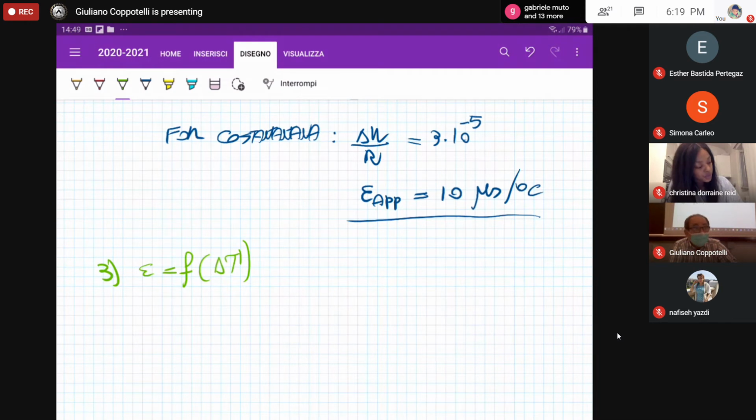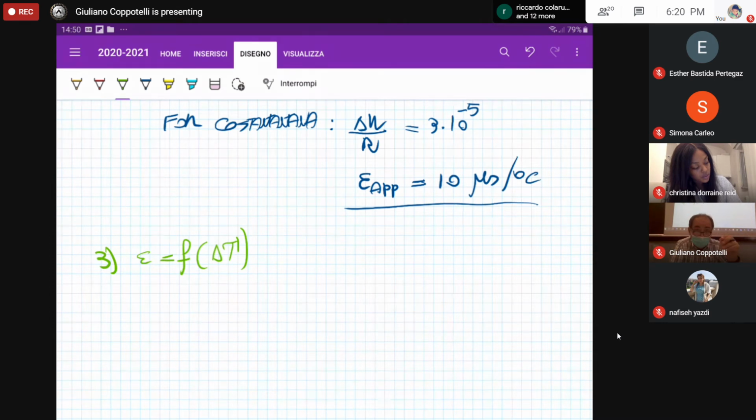Now, what we have to consider is that, once again, the measurement setup is telling me that we have to bond your strain gauge to the host structure. And therefore, I am sure that the bonding device is behaving ideally, that there is no bonding effect on my measurements, so that I can consider negligible all the bonding induced effects. So what we have just to consider is the strain gauge and the host structure properties with temperature.